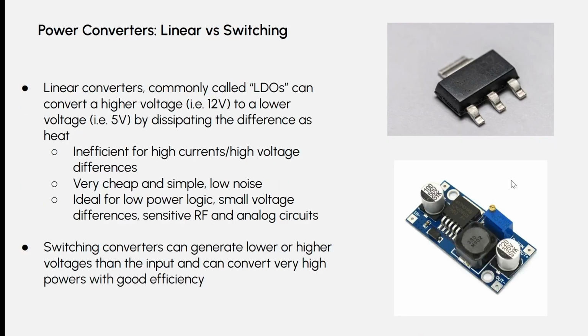Okay. We'll cover power converters. Power converters are very important in electronics. Generally, you will have some sort of input power, and it is extremely unlikely that your input power source will match exactly with every single chip on every single board. You are most likely going to need to generate some intermediate voltages to drive those chips.